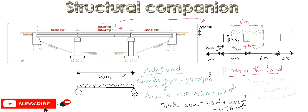So how much UDL will we have on this beam? It will depend on the area. UDL is always in kilonewton per meter. If I multiply this area and the unit weight of concrete, then it will give me the UDL which is applied on each meter of this beam here, which is the central beam of this slab.